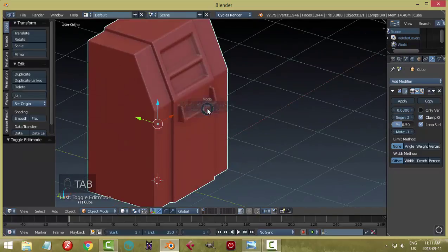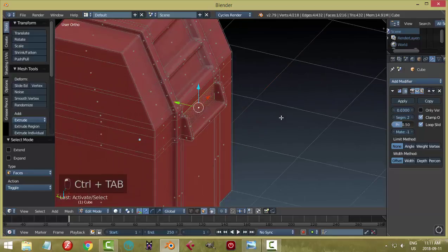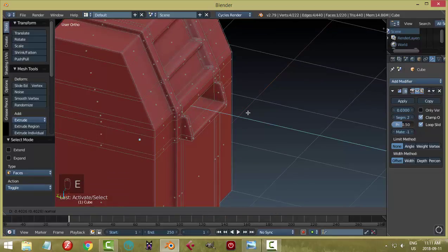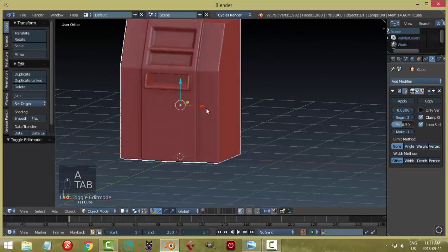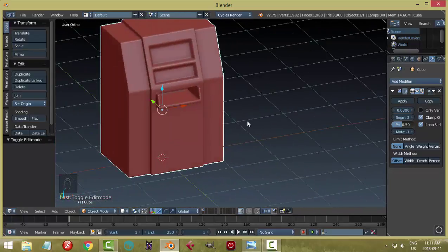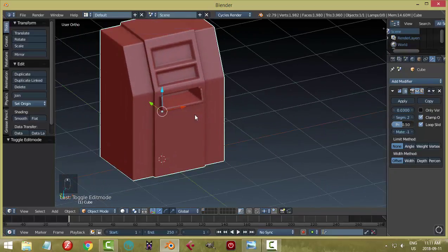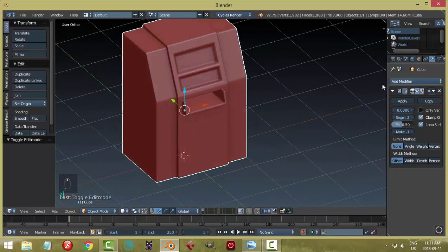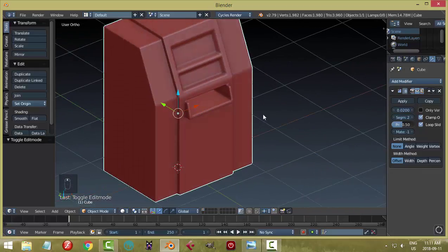Let's create the hole here. That's pretty easy to do. In face selection, select that. E to extrude and just push it in a certain distance. It doesn't have to go too far. Okay. So there we have that. And we're going to do some more work on that. We could do that right now. Notice I haven't applied the bevel yet. I'm leaving that. Let's try 0.02 and see if that does anything. It's not changing much, so that's fine with me.